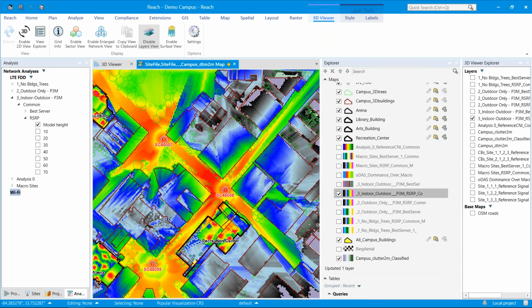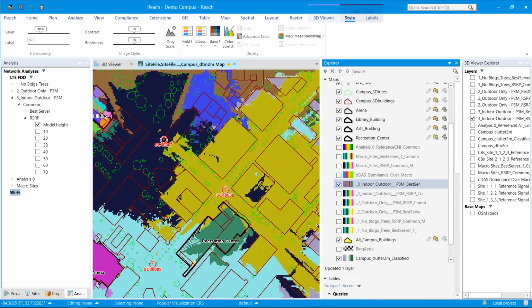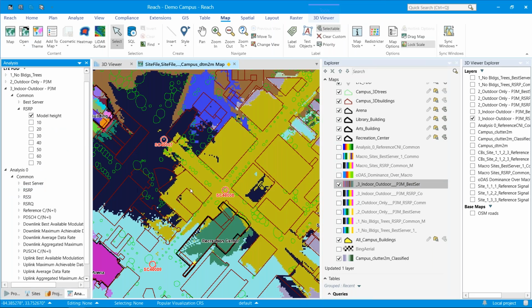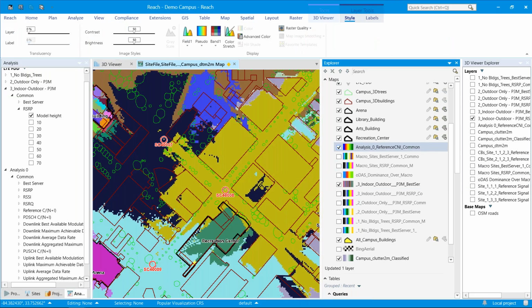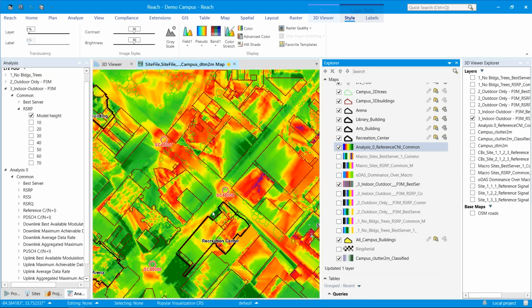In terms of questions, one is how to identify where the ingress egress takes place. Excellent question. You can do that a couple of ways. One, as I mentioned, is showing the best server to see where your best server is located. You can also do an analysis from SINR. I didn't bring one up for this particular area, since this is pre the system being deployed, but I did for the macro environment. So you can see the impact of where some of your handoffs will take place based on SINR.